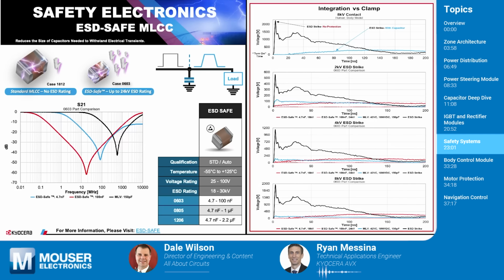So, we have really small sizes. I think we go down to 0402 on the ESD Safe. It's showing 0603, but I'm pretty certain we can go down to an 0402 high CV as well. But these are just great parts, and it's great to really just know. And most design engineers, I would say, know they need to protect against the ESD strikes and the transients, and it's just a really neat part in a small form factor that you can throw in there and keep the circuit safe.